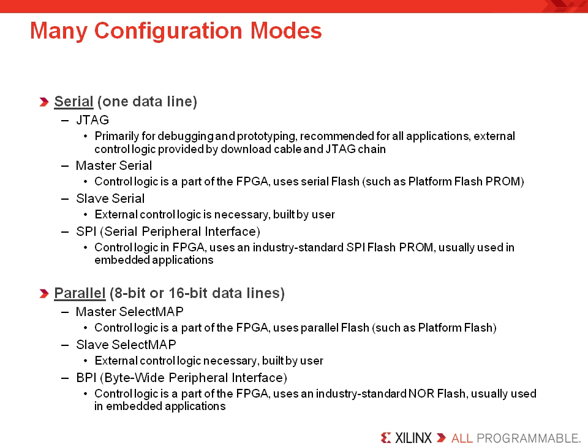Now, this slide will list all of the currently supported configuration schemes for all of our FPGAs. There are serial and parallel modes. First of all, parallel modes are inherently faster even though they may operate at the same speed since they configure the device a byte at a time. The primary advantages and disadvantages include debugging time, debugging effort, cost, and speed of loading the bitstream.